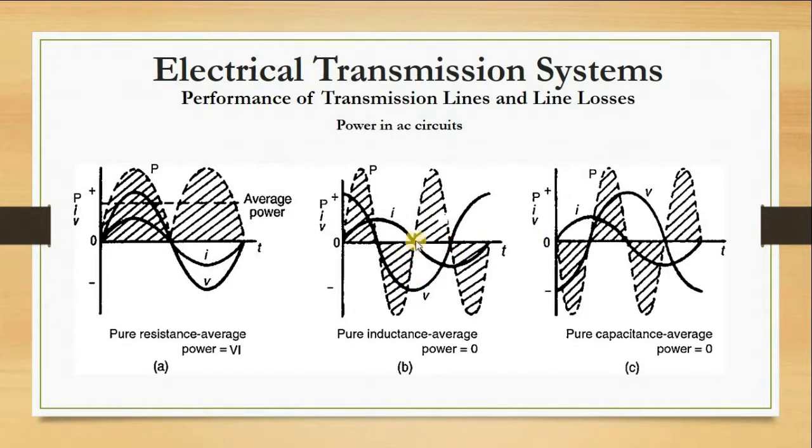Now, once you have understood this for the inductor, the capacitor is always the other way around. While in an inductive circuit the voltage leads the current by 90 degrees, in a capacitive circuit the voltage lags the current, also by 90 degrees. If you can see it well, you can bring all of them to one point. Now if you extend this here, this is the voltage waveform and this is the current waveform.